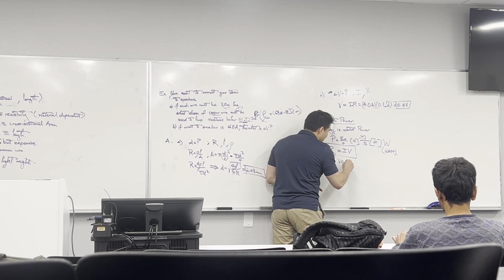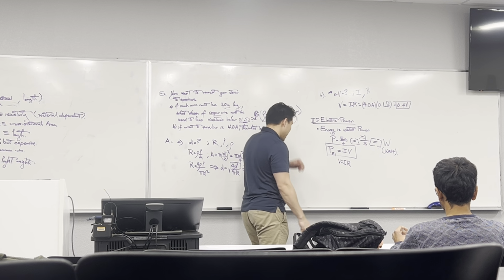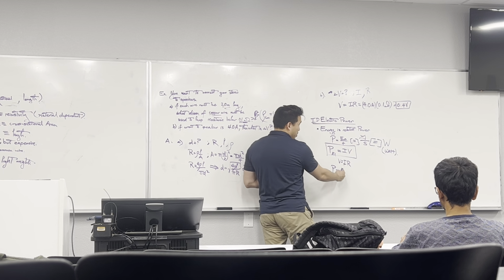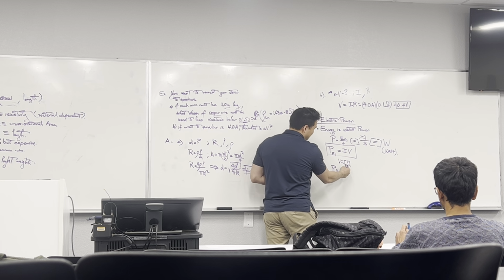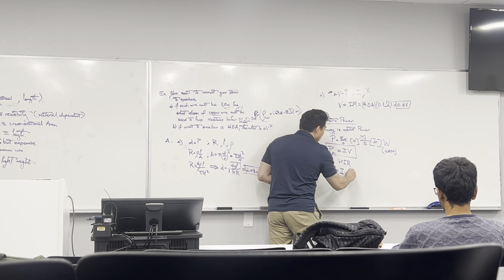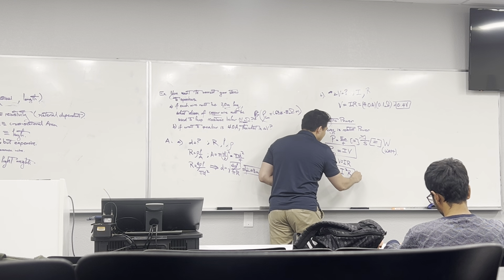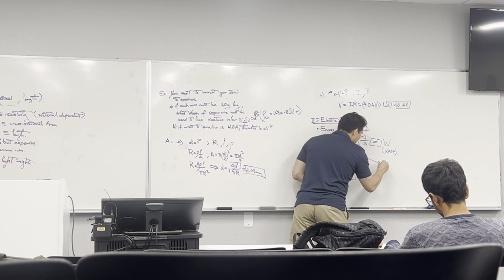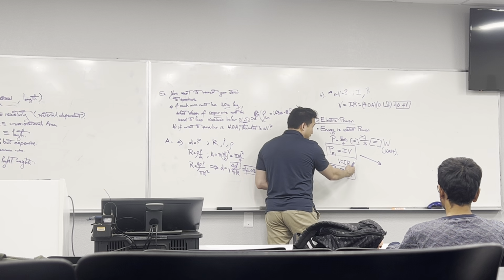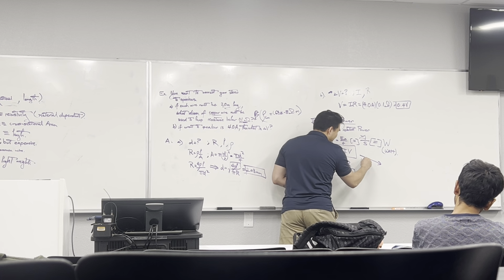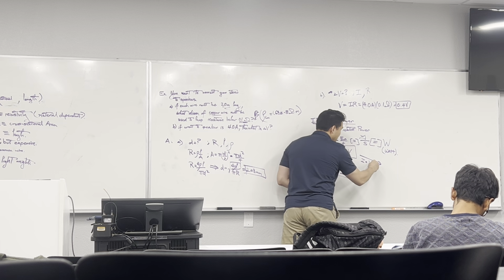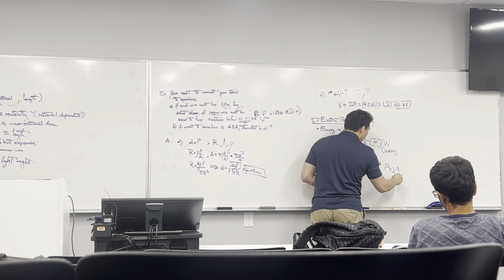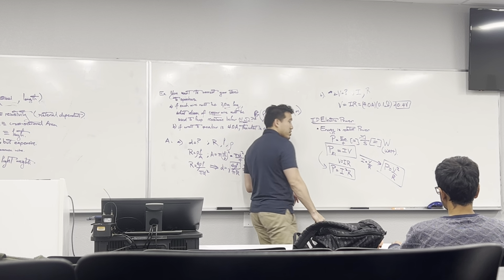Of course, we can use V is equal to IR, Ohm's law, and transform this into P is equal to, substitute IR in for V here, and you're going to get P is equal to I squared R. Or alternatively, instead of V is equal to IR, we can replace I, just rearrange Ohm's law a little bit for V over R, and you'll get P is equal to V squared over R, and those are alternate forms.